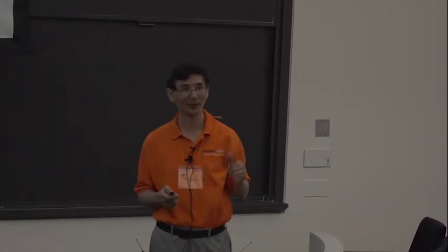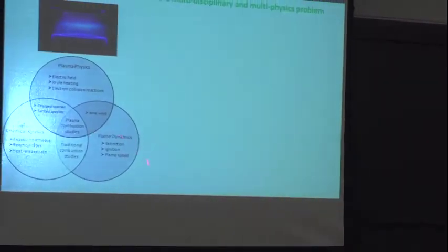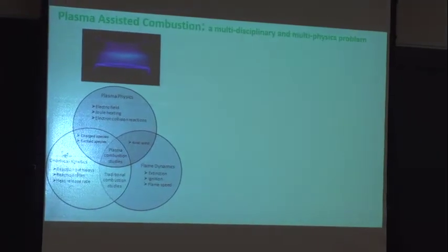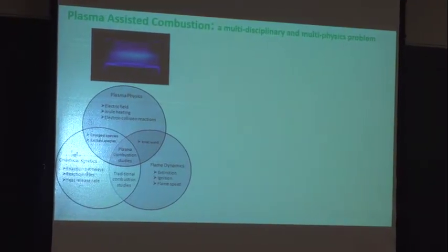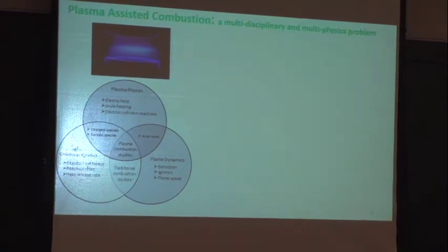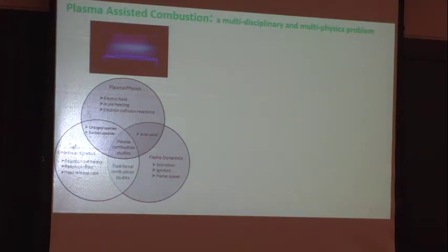If you have an electron beam or a plasma to generate radicals right away, that process can be dramatically accelerated. This is one way that the plasma can control an ignition process. In combustion, you have extinction, ignition, and flame speed, and you do want the plasma to control all of them. To understand this, you have to understand the reaction pathway. That means: my electron impact reactions, which reaction is really being perturbed, and enhances the combustion, right?